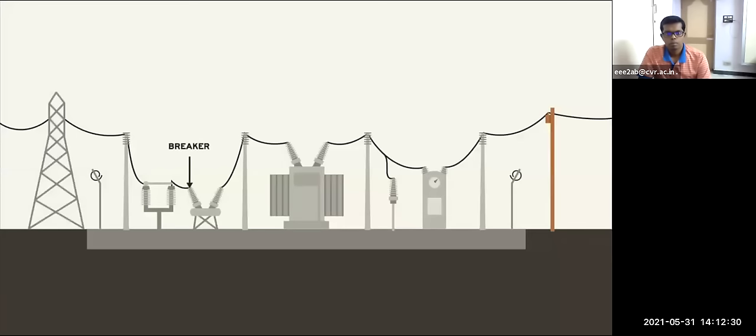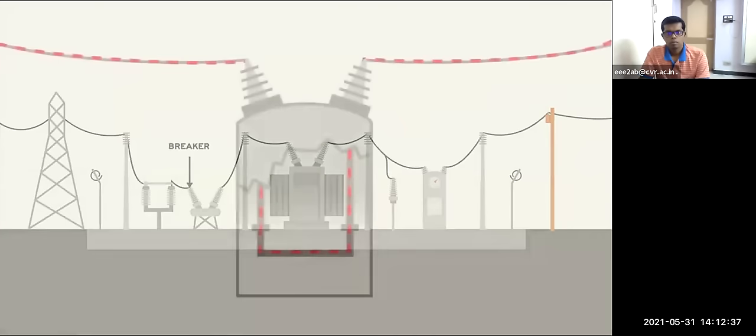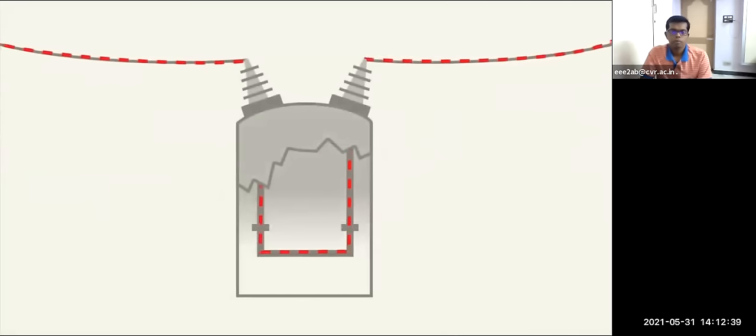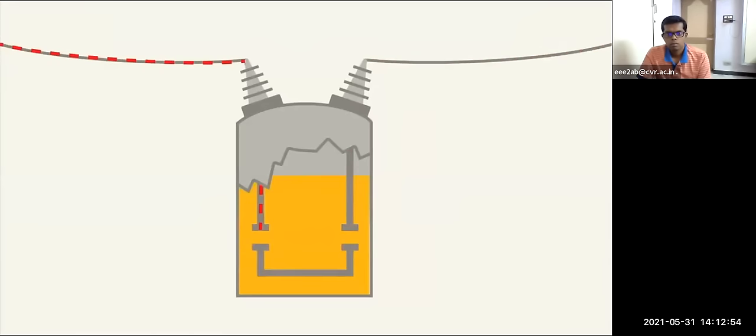On the other hand, circuit breakers are a class of device that serves similar roles as fuses, but provide more sophistication for dealing with a wide variety of faults. Like disconnect switches, circuit breakers need to be carefully designed to interrupt huge currents without damage. As soon as contacts within a circuit breaker are moved apart from one another, an electrical arc forms. This arc needs to be extinguished as quickly as possible to prevent damage to the breaker or unsafe conditions for workers. Extinguishing the arc is accomplished by a material called a dielectric that doesn't conduct electricity.